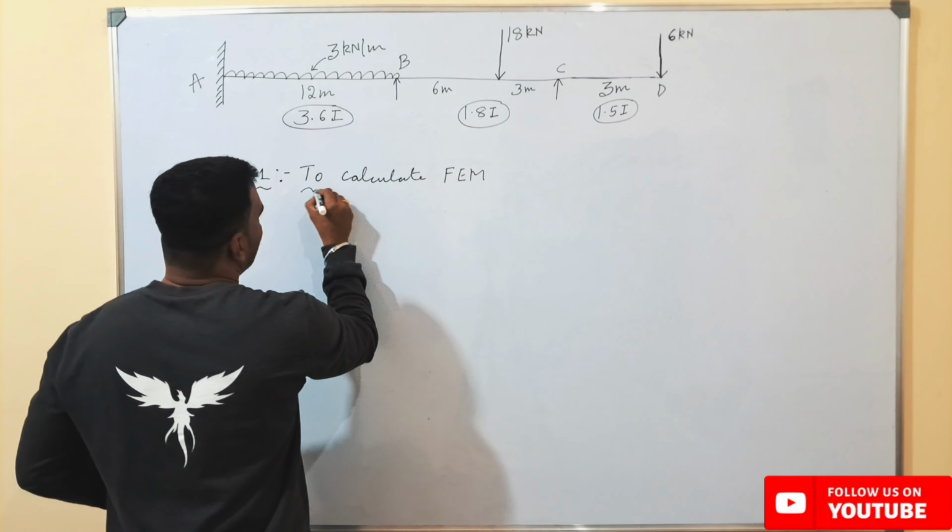And here inside this box we have to write the rotation factor, whatever we have got in table 2 in step 2, that is from B to A we have to represent here, and from B to C we have to represent the rotation factor here inside this box. So we know the rotation factor from B to A we have got is minus 0.333, and the rotation factor from B to C we have got minus 0.167. So using these values, I need to calculate the